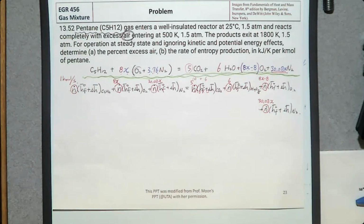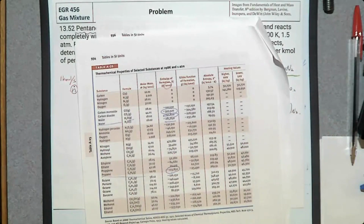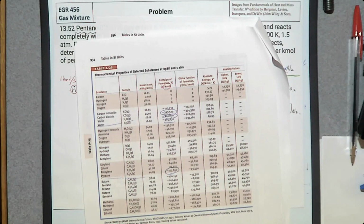Now, let's determine the enthalpy of formation for each component. How do we determine the enthalpy of formation? You go to table A-25. Here, the enthalpy of formation is listed. For the first four components, carbon, hydrogen, nitrogen, and oxygen, the enthalpies of formation are 0.